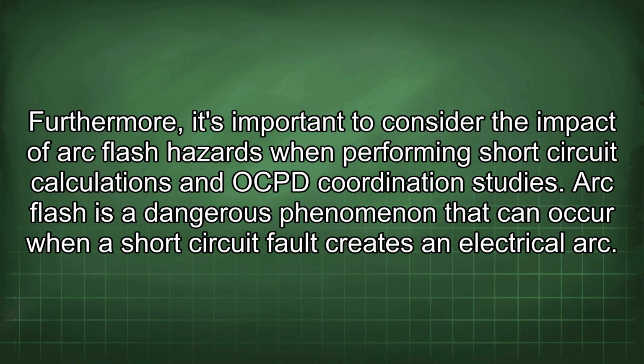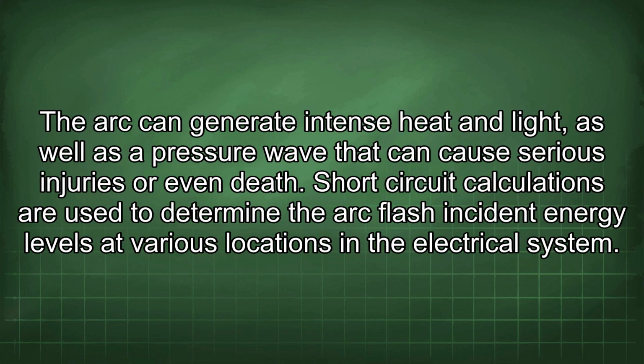Furthermore, it's important to consider the impact of arc flash hazards when performing short-circuit calculations and OCP coordination studies. Arc flash is a dangerous phenomenon that can occur when a short-circuit fault creates an electrical arc. The arc can generate intense heat and light, as well as a pressure wave that can cause serious injuries or even death.